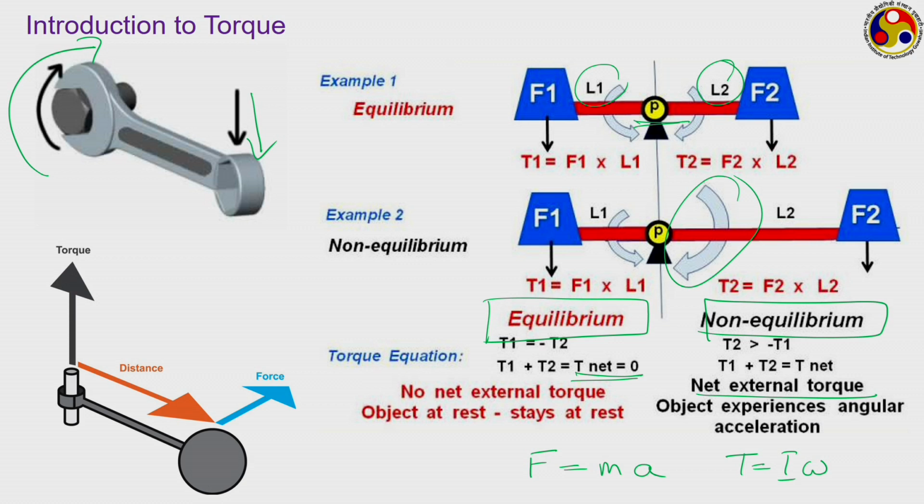Now, torque measurement is quite commonly related to the measurement of power, because whenever you are talking about a shaft rotating with a particular RPM, and a torque is applied on it, we can easily relate the torque and its angular velocity to the power which we can get from this shaft if we are talking about a power producing device, or how much power the shaft is absorbing if we are talking about a power absorbing device.